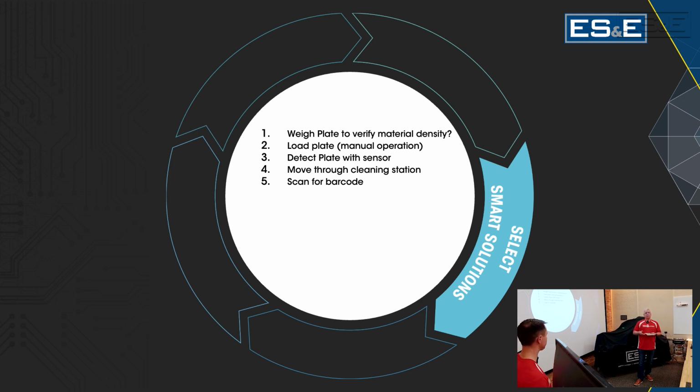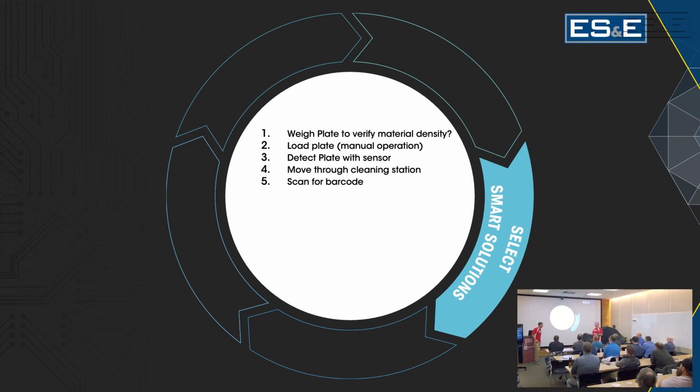to your control system. Now, you say it's going to stop in the same place every time, but I know that conveyor motors can get slack in them, all that good stuff. So how do we make sure that the plate's going to stop exactly in the right place, so it positions itself where the camera's supposed to be and it can actually read it? We'll use a servo. Oh, we'll use that. Use a servo motor on the conveyor. Yeah, that's right. So that way we know that it will come to the same exact spot every time.